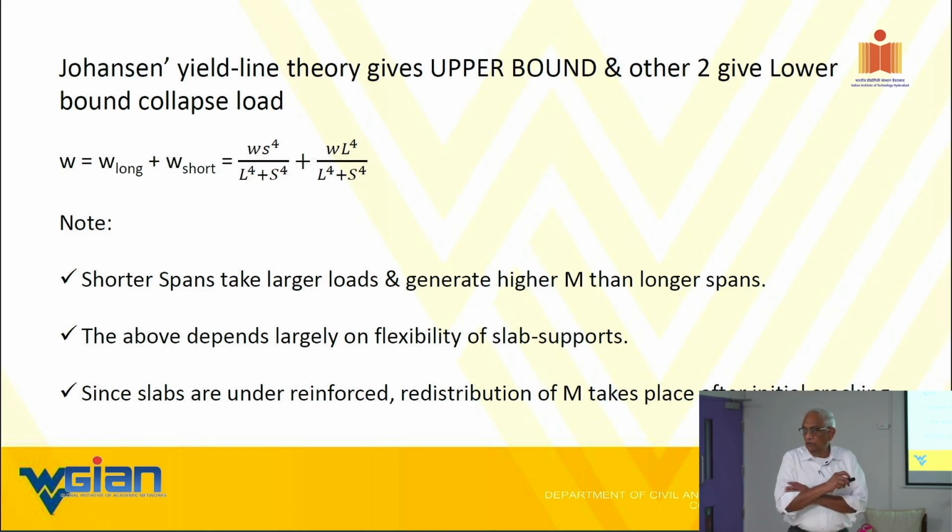See, the short side direction is what is going to drive the design of a frame, not the long side. We can use short and long side type stuff to make the design more efficient.